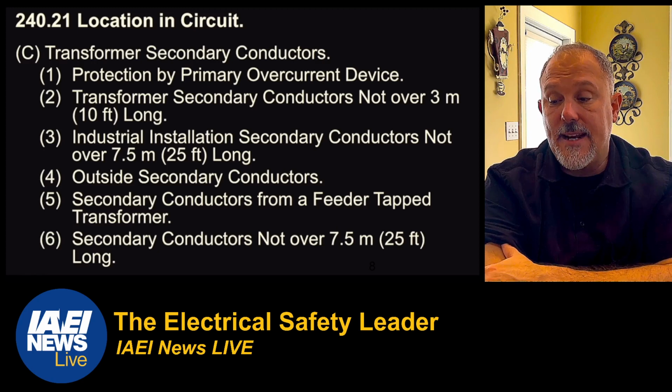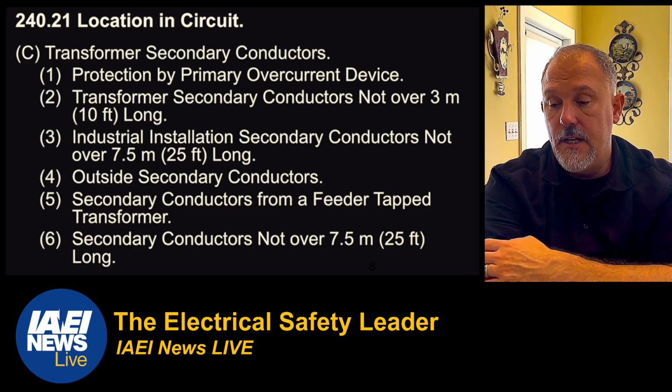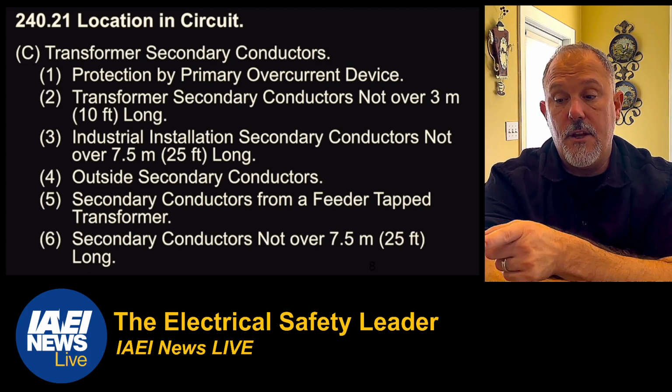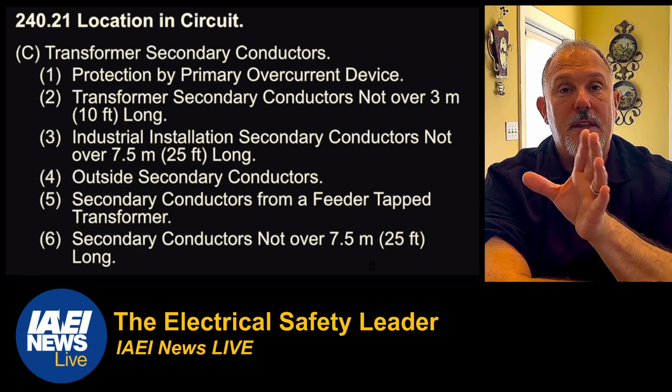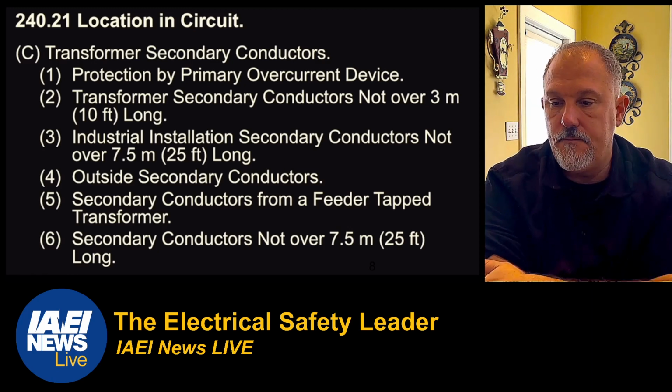And then you have secondary conductors from a feeder tapped transformer, which is not what we have. And then secondary conductors not over 25 feet long. And then item 3 is industrial installations, secondary conductors. So they treat industrials a little different than, say, commercial buildings.